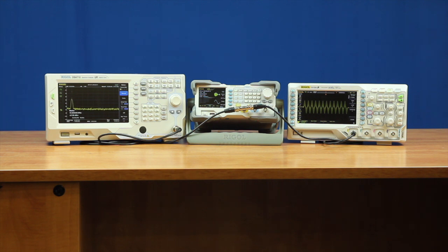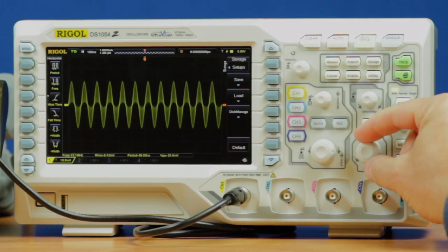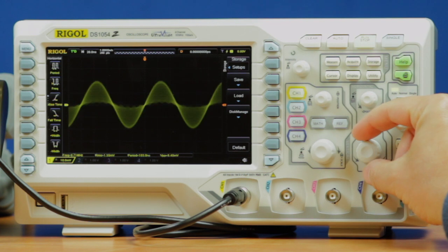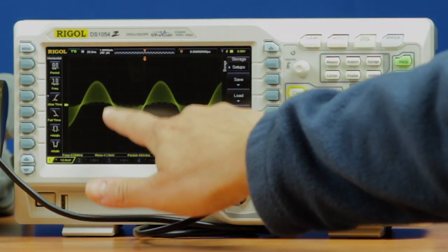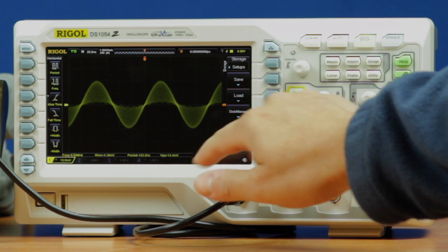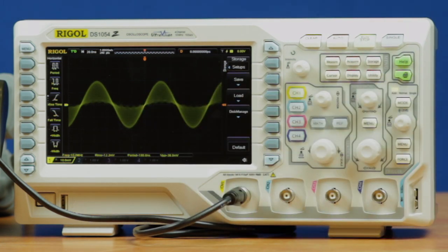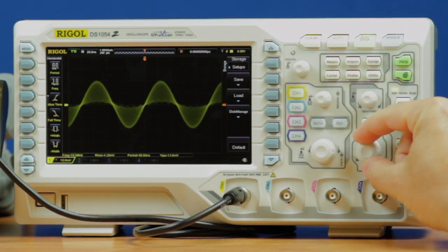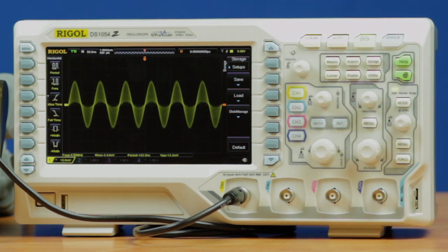So now that we understand how we convert amplitude and voltage into power, let's look at our next demonstration, which is really about amplitude modulation. Here I've set up the AM modulation setup files for the generator, analyzer, and oscilloscope. We can see here on the oscilloscope how, with this amplitude modulation file, the signal is often at full amplitude, but sometimes comes in smaller. So as the amplitude changes, you're getting multiple wavefronts shown on the instrument. That's how it appears in the time domain.